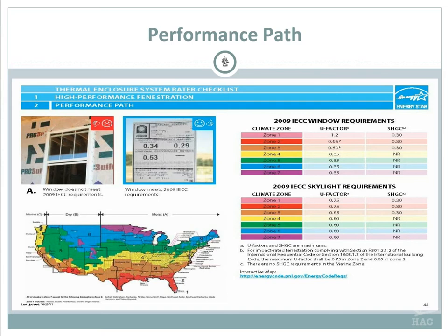These are the minimums. Again, these are going to be the minimums that you're allowed in order to meet your performance path. Anything less than this, it's not going to meet it, or higher numbers than this, it's not going to make it. Again, skylights, as you can see, they're pretty much the same. It's only about 10 R values, a little bit different on the bottom there, and a little bit higher for the skylight requirements. Again, we talk about skylight requirements and U values.